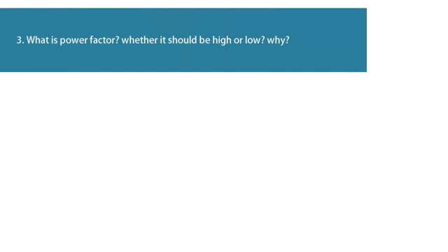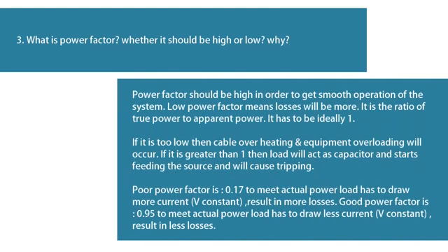3. What is power factor? Whether it should be high or low. Why? Power factor should be high in order to get smooth operation of the system. Low power factor means losses will be more. It is the ratio of true power to apparent power. It has to be ideally 1. If it is too low, then cable overheating and equipment overloading will occur.